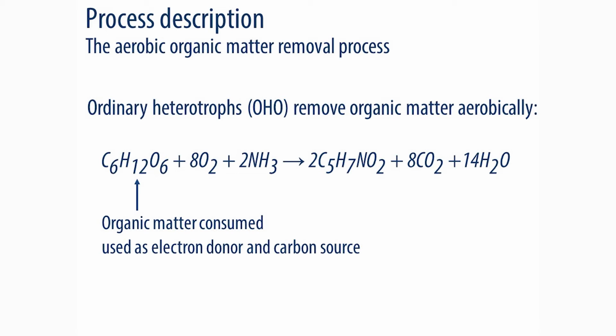In conventional wastewater treatment systems, the aerobic removal of organic matter is carried out by ordinary heterotrophic organisms, OHOs. Under aerobic conditions, OHOs consume the organic matter and use it as an electron donor and also as the carbon source to produce new cells.